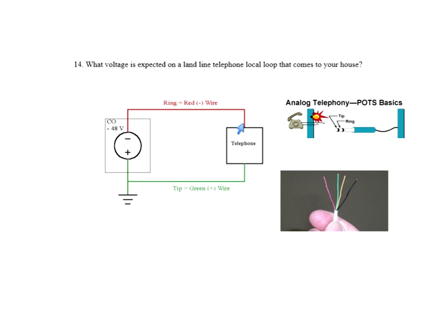So this wire here is called the red ring wire. It's red. Where does that come from? Well, it comes from this. On the old telephone plug for the operators, it was the ring on the plug. The tip is the one that's grounded right here. The tip wire is the green one. It's grounded. It's called the tip.